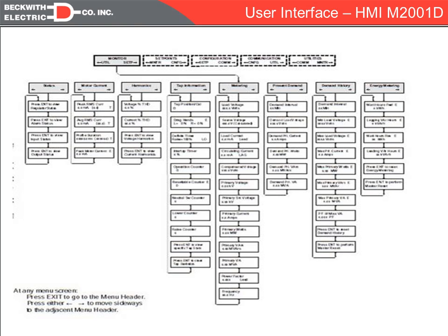And each of these menus at the top has hot links off of the push buttons on the front of the control. So MON is monitoring, SETP is set point, CON is config, COMM is communications, and our last one is utilities. Once you hit a button, if you look at the bottom part of the screen and hit the left or right arrow, it'll tell you the next topic you'd be going into. But once you get to a topic that you like, if you hit the down arrow button, or you hit the enter key, it'll drill you down.